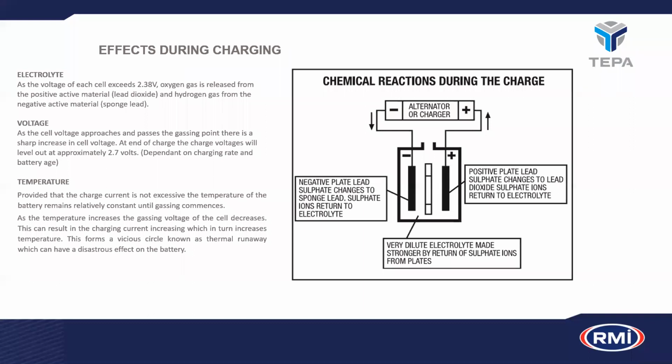We had one instance where a business was continually complaining that the batteries that they sent in for claims were being rejected for overcharge, and it so turned out that that particular business's battery charger had not been calibrated, and where they thought they were doing a charge at 5 amps, they were actually doing a charge at 25 amps, and they were literally destroying all the batteries on their charging bank. So it's quite an important thing to bear in mind during the process.